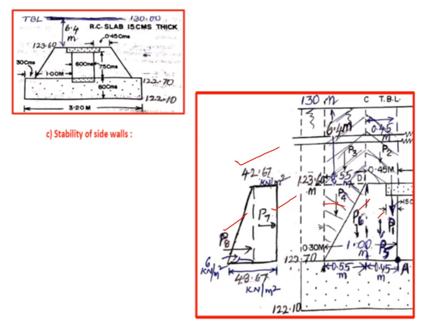So like this. So now you know that P1, P2, P3, P4, P5, P6 is making anti-clockwise moment about A. So they are entered in the resisting moment, whereas P7 and P8 are making clockwise moment. So therefore they are entered in the overturning moment. So this is the calculations part for the stability.